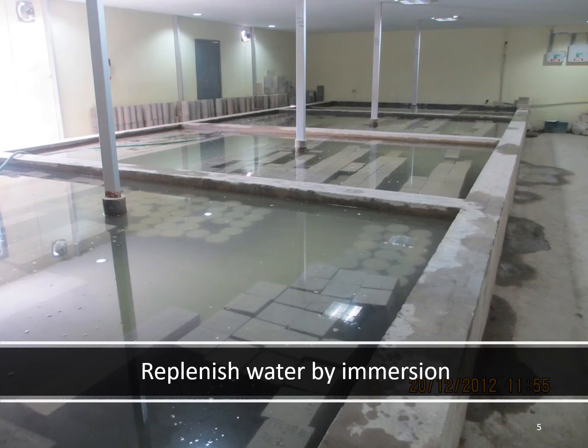The third important thing is that the curing tank made in the project or at any testing laboratory needs to be covered under a roof, so that direct sunlight will not have an impact on the temperature of the water. So this is the requirement as far as the replenishing water by immersion methodology is concerned, and it is generally used in testing laboratories to cure the cubes.